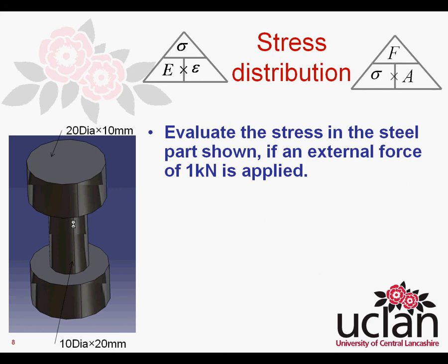The clues which can be given are from the last slide really, is this particular component comprises of two different cross sections, one of 20mm diameter and the other of 10mm in diameter. It is these that need to be used in the stress calculation, force divided by area. So if you could try and calculate that out and come back, we'll give you the solution in the next segment.